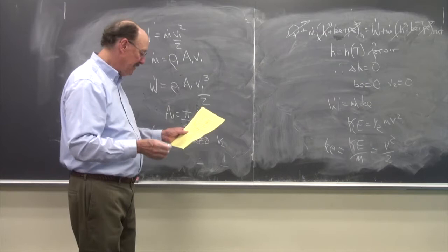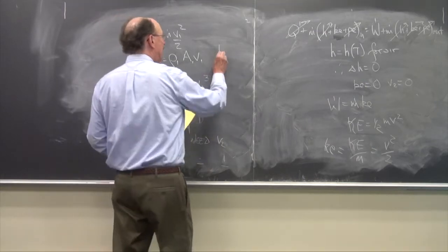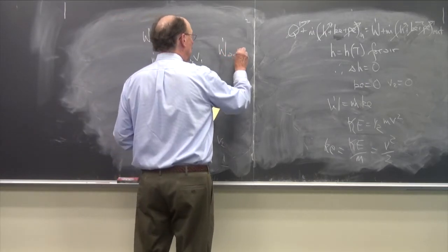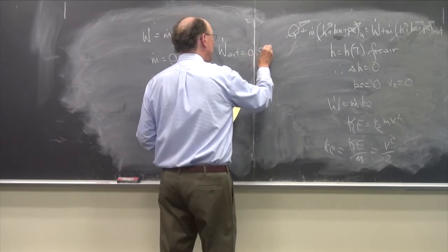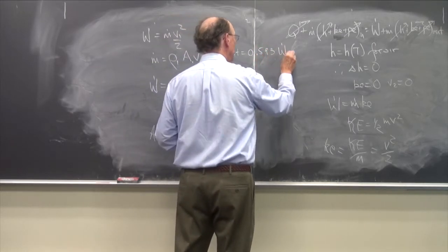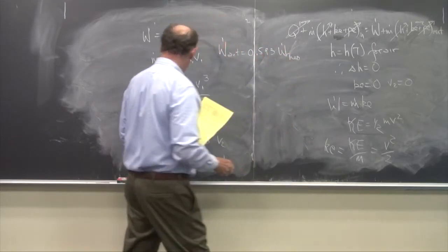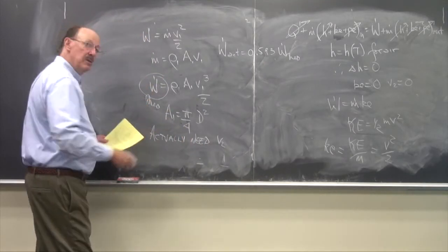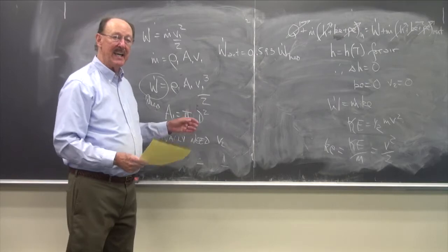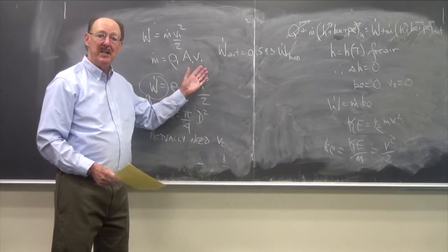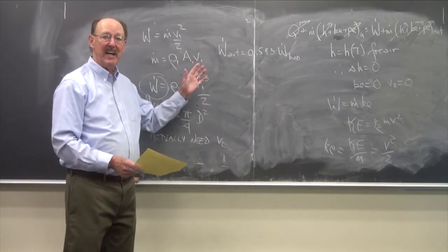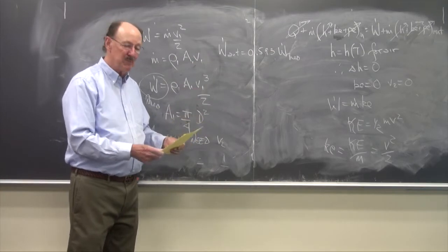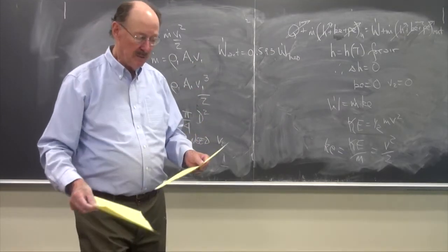And so with that, the W dot actual is about 0.593 times W dot theoretical. So it's about 60% of that is the best you can do, and then you bring in all your other factors that reduce it more in terms of mechanical efficiencies, etc.